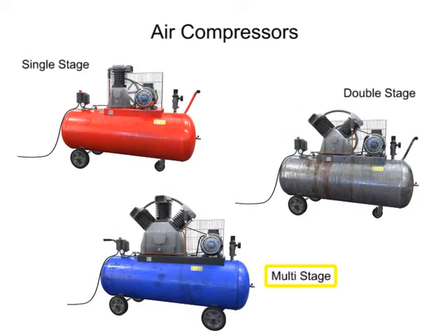On these larger compressors, cooling may take place by circulating water instead of air. To reach a pressure of 2500 psi, as many as 6 or 7 stages may be needed, with cooling between each stage. Their versatility makes compressors one of the primary components in air production.